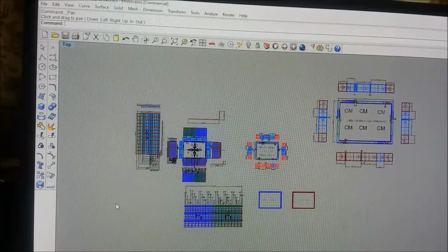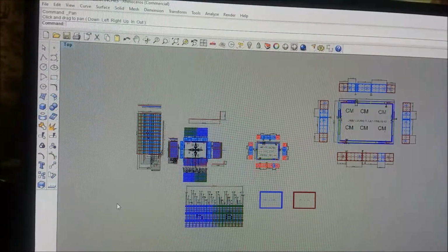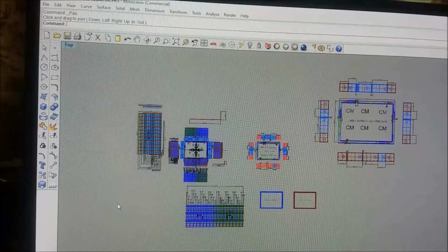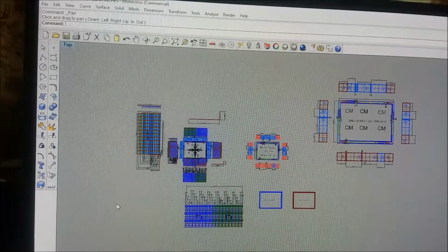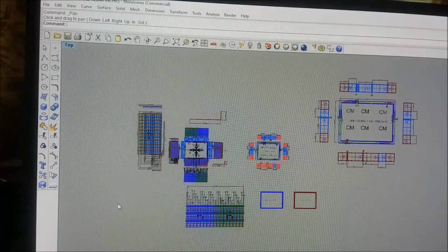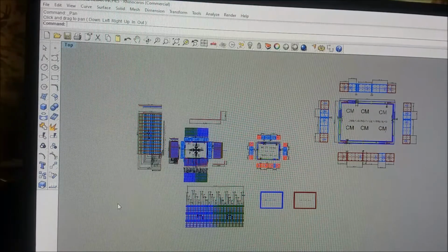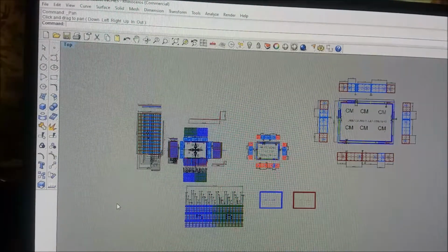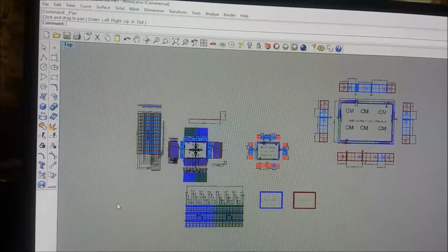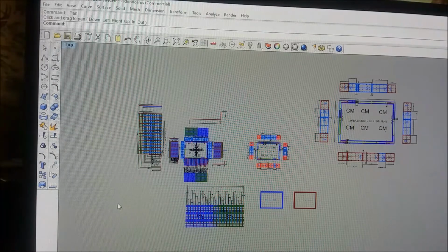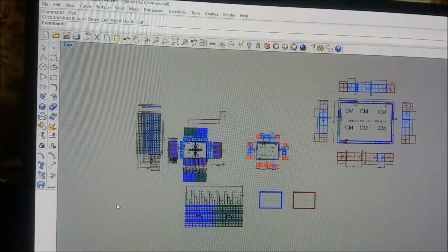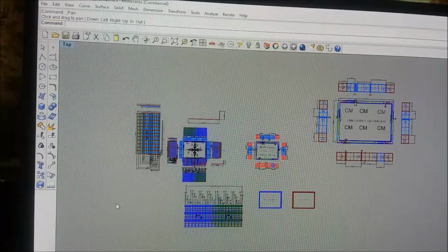If you see him pouring a slab that you're going to be sleeping underneath of, and the rebars are 20 inches apart in number 10s, you might want to look at the first video of this series on slabs. You'll see they're supposed to be much closer. We calculate them on the narrow span. However, if your room is square or even close to square, then you can use all of them in the calculation because there's not one being stressed more than another on a square room.